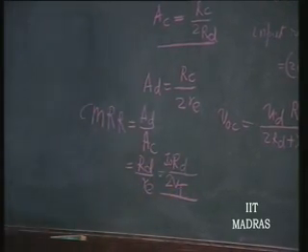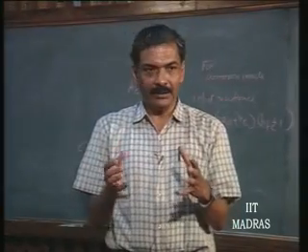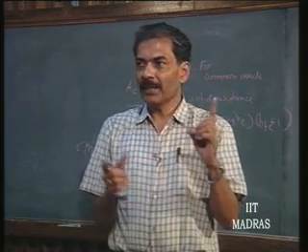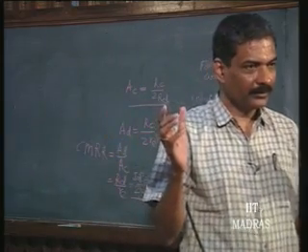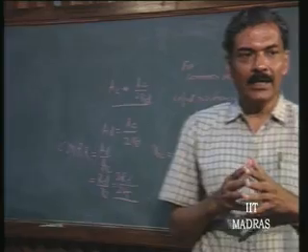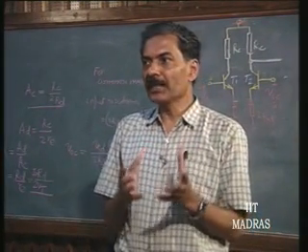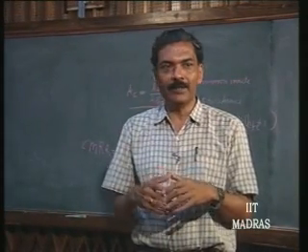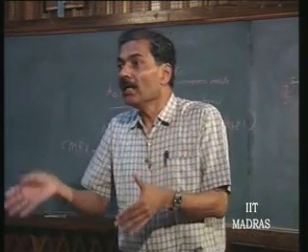Now, we have quantified every one of the small signal parameters associated with the differential amplifier in terms of the load resistances as well as operating current, including its swing. So, now you can design depending upon where it is going to be used. Is it going to be used as the input stage of an op amp, or in a video amplifier where the stage itself has the responsibility of input and output?